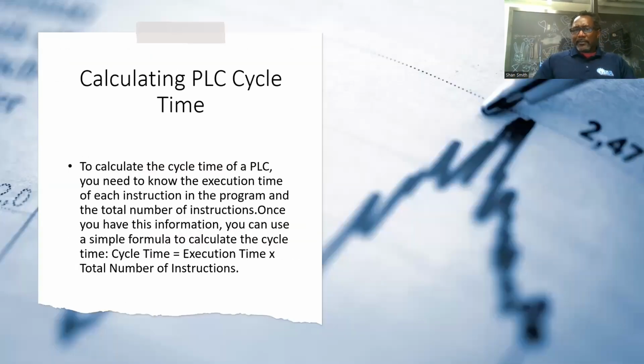We mentioned a few minutes ago that you can calculate cycle time. But if you know the controller and you know your I/O, that's going to be the best way to do it. To calculate the cycle time of a PLC, you need to know the execution time of each instruction in the program and the total number of instructions. Once you have this information, you can use this simple formula to calculate cycle time. Know your controller, know the product you're working with, and you can have a very good approximation of how much horsepower you're going to need for that controller. Maybe it's overkill, okay?